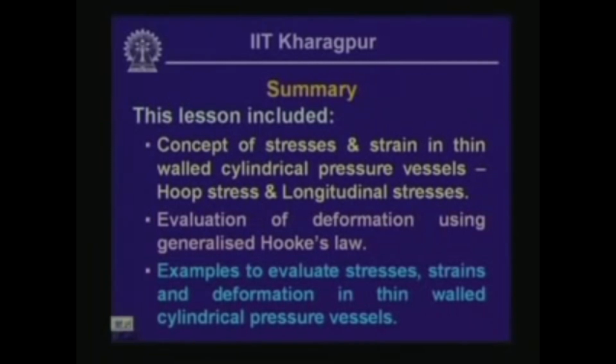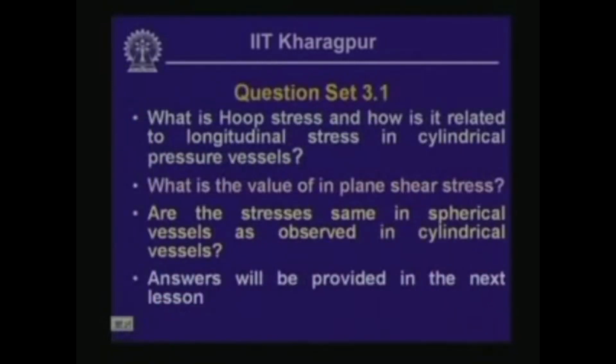Well, to summarize, we have discussed the concept of stresses and strain in thin walled cylindrical pressure vessels, and thereby we have discussed hoop stress and longitudinal stresses, evaluation of deformation using generalized Hooke's law, and examples to evaluate stresses, strain and deformation in thin walled cylindrical pressure vessels. The questions set for you are: What is hoop stress and how is it related to longitudinal stress in cylindrical pressure vessels? What is the value of in plane shear stress, and are the stresses the same in spherical vessels as we see in cylindrical vessels?